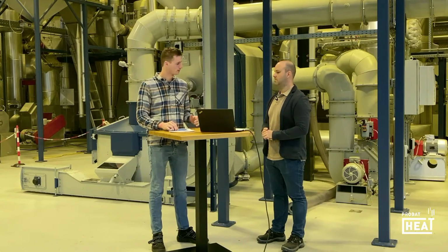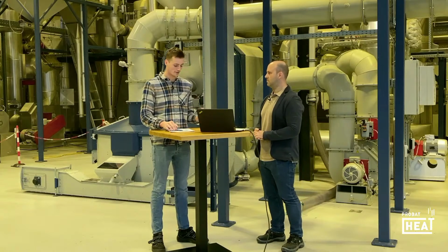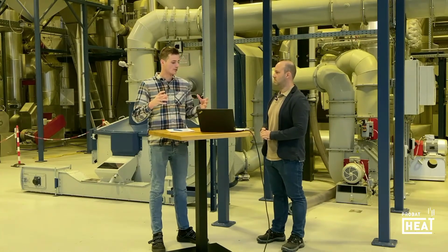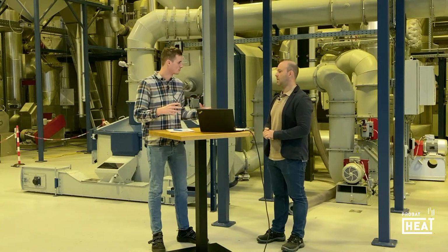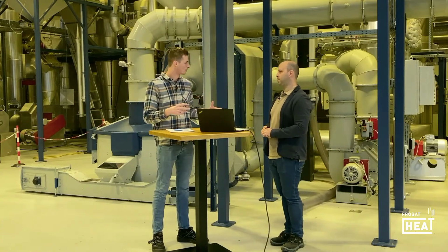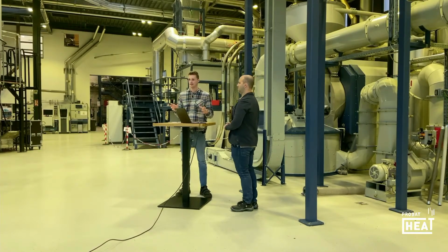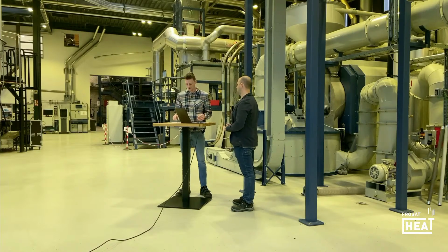For this we monitor a wide array of different things, which are temperature, because the rolls need to have a specific temperature, and being water cooled, when they deviate in temperature, the spectrum of the grind changes. So we monitor the temperature and take measures to always keep it in the right area.